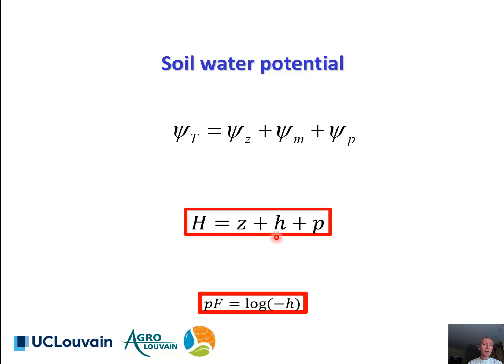If the soil becomes wetter, soil water will mainly be situated in larger pores. In these soil pores, the capillary forces will be less. Hence, capillary forces will decrease with water content. This is mainly due to the fact that an inverse relationship exists between capillary force and capillary radius, and that larger pores contribute to the soil water status when soil wets up.